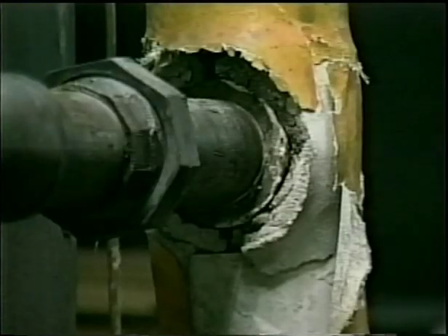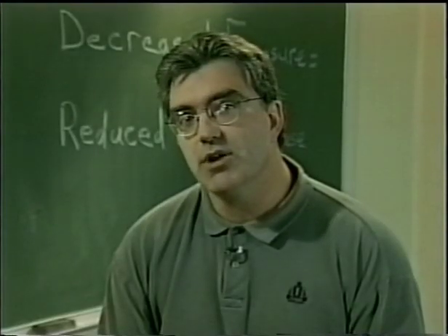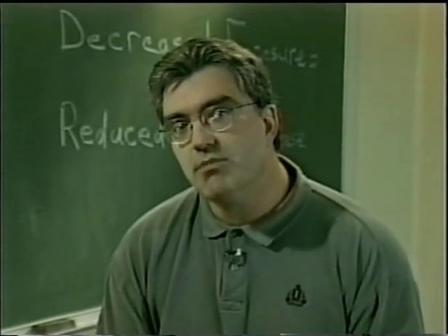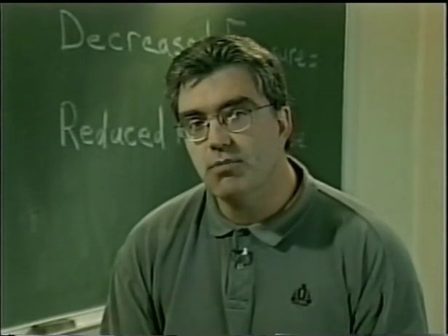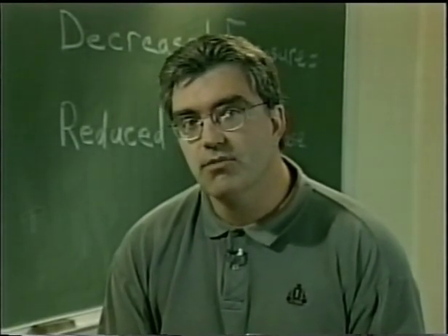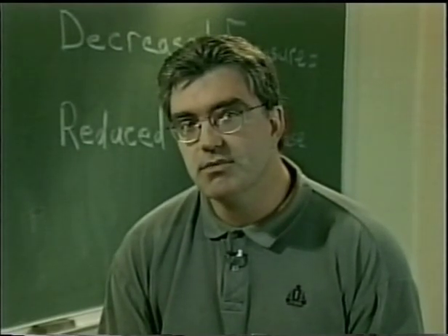Do not attempt to clean up spills yourself. Disturb the material as little as possible. Also, report any damaged pipe insulation, ceiling tile, 9-inch floor tile, fallen clumps of sprayed-on insulation, etc. Take measures to prevent others from disturbing the spill until the asbestos abatement crew arrives. By knowing where asbestos is located in your facility and taking measures not to disturb it, you will protect yourself and others from this hazardous material.